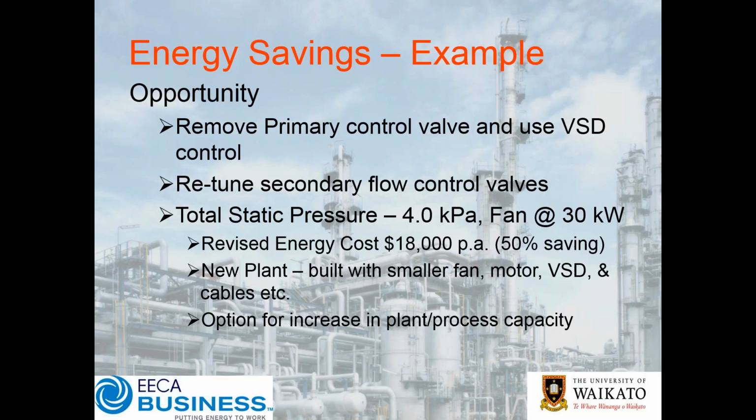Now, a new plant built replicating this design was able to be built with a smaller fan, a smaller motor, a smaller VSD, and smaller cables. So getting it right also enables you to save substantially on capital and reduces the size of spares that you need to maintain. The irony, or additional benefit, in this particular situation is that it gives you the option to still have additional capacity in the process without having a grossly oversized system.